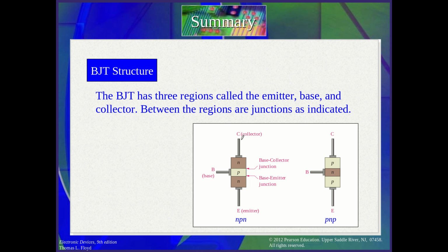Now let's see what a DC load line is. The DC load line is the line connecting the saturation point to the cutoff point, this line. So the transistor characteristic curves are shown here and superimposed on the load line. The region between the saturation region and the cutoff point we call the active region, as we saw before.